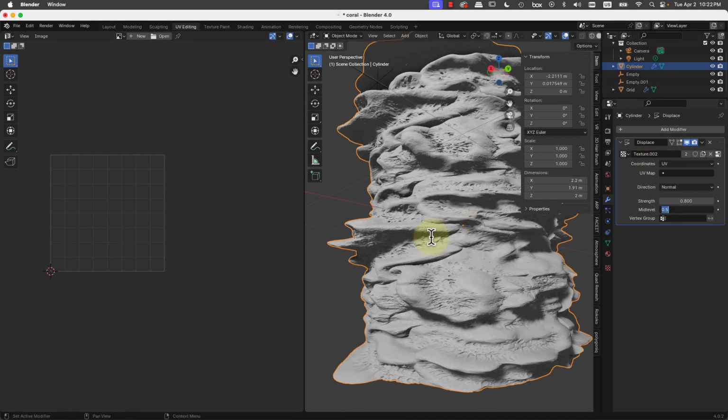Once you finish this, always decimate the thing before sending it to 3D print or whatever. Okay, because if you don't do that, it's going to take forever. It's going to make things slower, and you're going to say that you need a faster new computer, which is not true. You just need time and decimation. In this moment I need time and decimation, that's it.